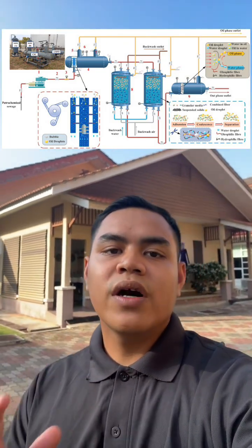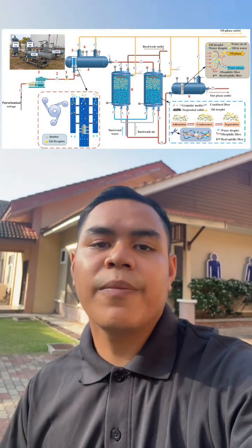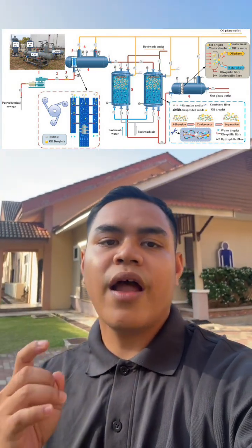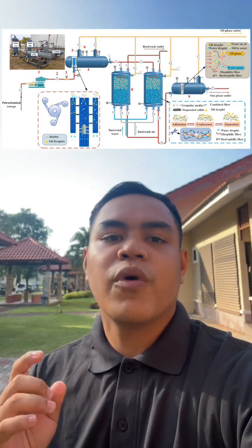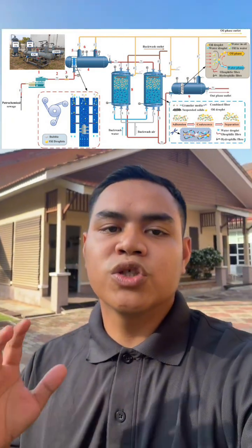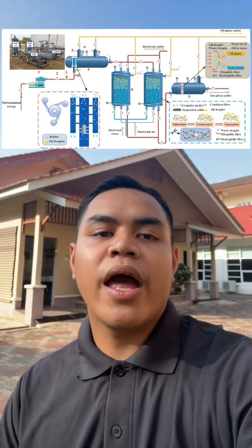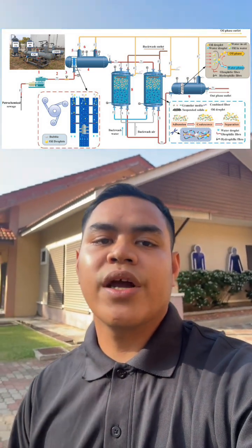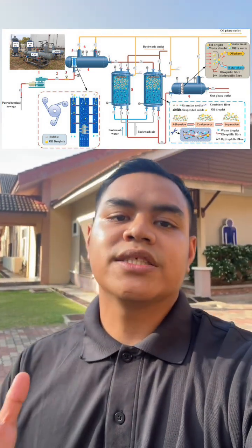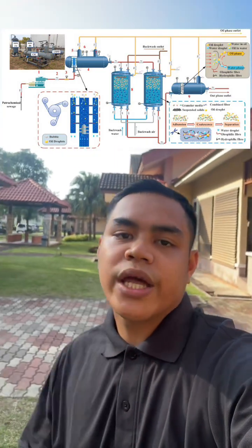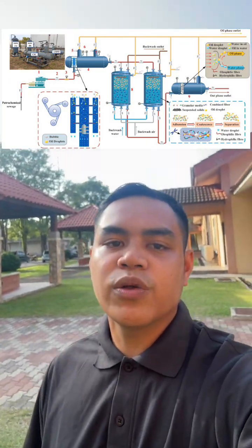Number 9 is reverse osmosis. RO uses high pressure to remove dissolved heavy metals and organics, producing highly purified water. Lastly is RO storage and reuse. The clean water is stored and reused for industrial processes, irrigation or safe discharge, supporting sustainability. Together these steps transform wastewater into a valuable resource, and thank you for listening.